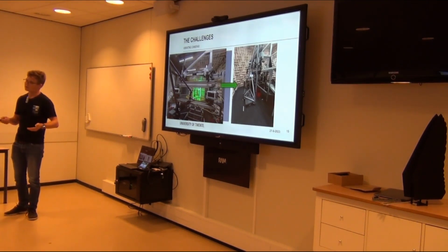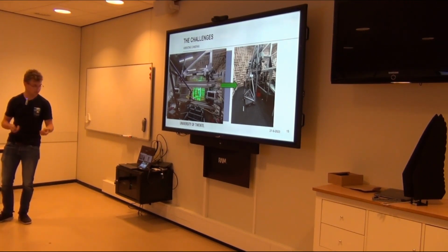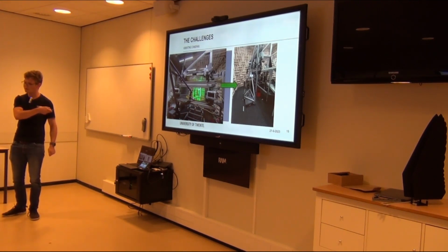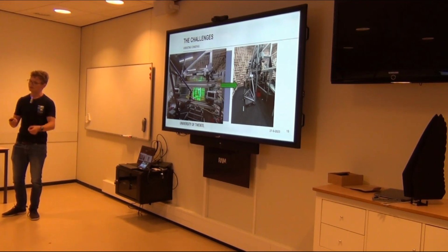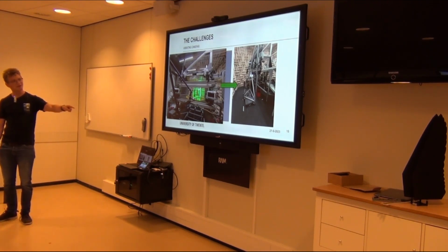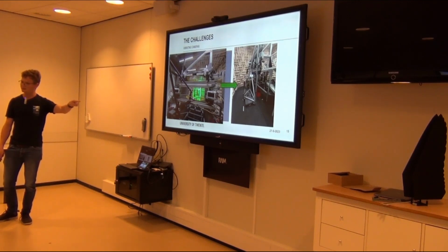Setting aside what to make of all this, one thing I would like to show you is all the challenges that we had to overcome to even do these measurements. First of all, we started with a setup where we had the cameras stably attached to the wind tunnel, and on that same wind tunnel we mounted a flapping wing, so that introduced all kinds of vibrations, and our calibration just turned to mush within 2 measurements. So we had to build a separate frame for it. We very carefully selected the right size rubber feet for it, and then we had to put a huge weight on there to dampen all of the vibrations coming from the tunnel as much as we could.